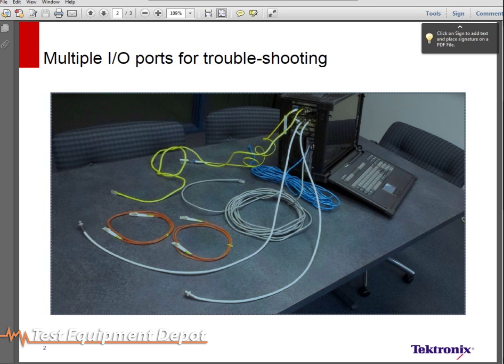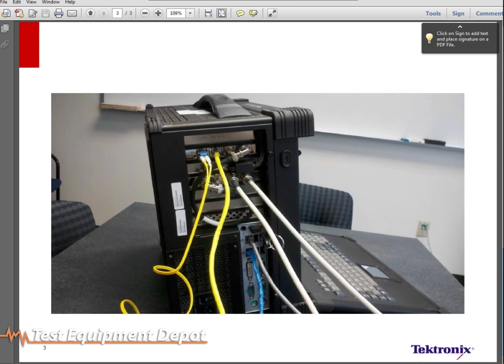The MTS4000, seen here on the right side, has a variety of cable connection points, whether it be Cat5, fiber optic, 10 gig, ASI, coax cable for ASI or for RF signals. So there's a variety of different connections that we'll be making use of today as we step through this application. And then on the side we can see that the current configuration right now has a single mode fiber duplex for the IP card on top. We have the two white cables that are jumpers for our ASI in and ASI out, and then below that we also have the capability for additional RF.